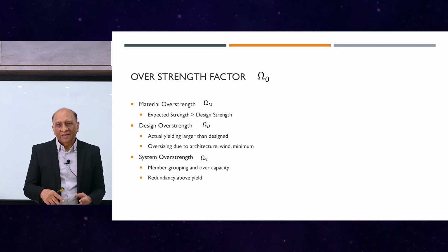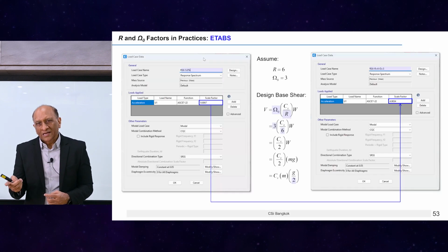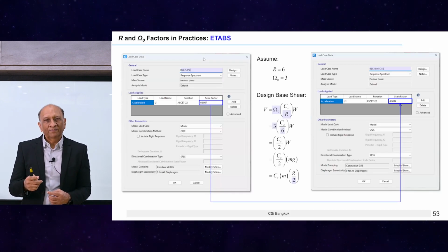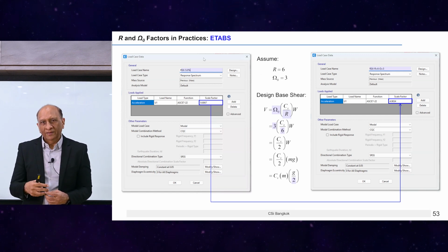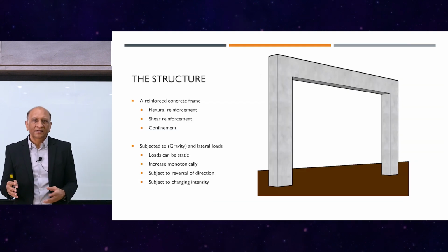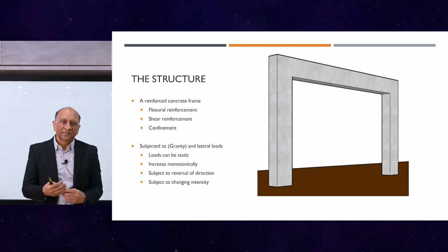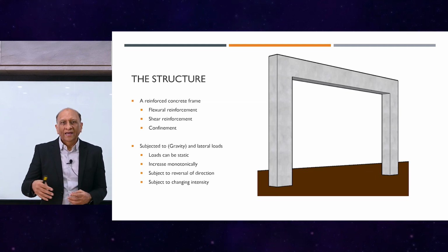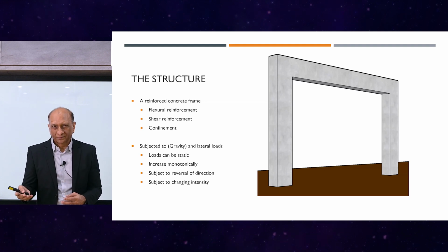So we go back and take that whole frame, once again taken from ETABS, and we include the capacity of the column, as well as the moment curvature of the column and beam. Then we put in this nonlinearity, which incorporates the material nonlinearity as well as the section nonlinearity computed from the actual provided reinforcement, and then we generate the hinges, put it back into the model, and do a pushover.